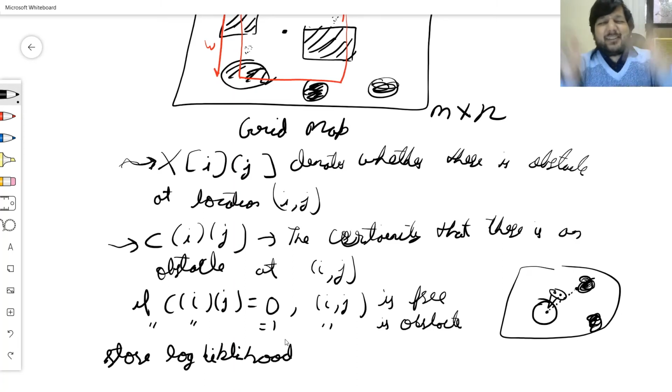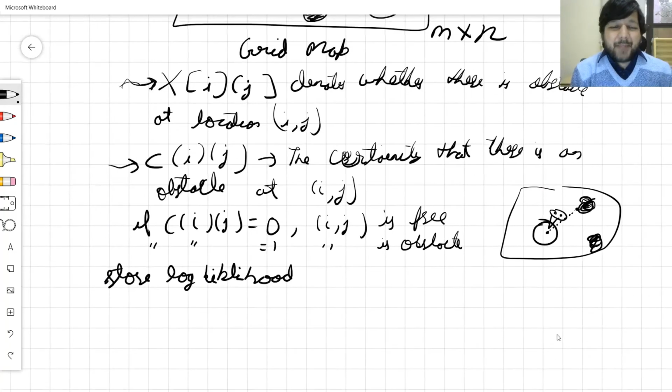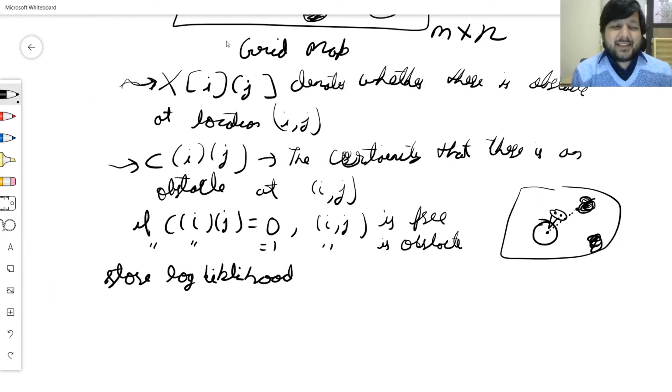And that's practical robots. The robot will keep getting confused whether a point is an obstacle or not. So practically when the robots move around, this is most practically what we get by continuously getting information whether a point is obstacle or not obstacle. So I store it as a confidence map or I store it as a certainty map.